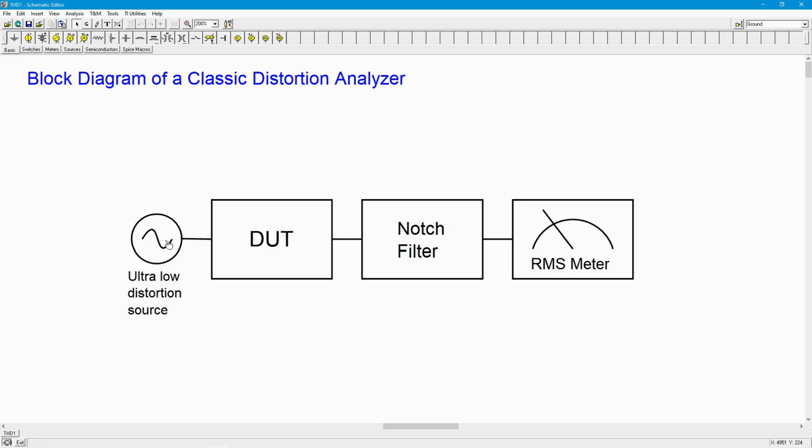So here's an error that some people will make. Let's say, and I'm going to use very simple numbers, that this thing has a 1% residual THD, which would be an insanely high number. I understand that, but this is just for simple mental calculation. I would expect something like 0.001, maybe lower, for a quality ultra-low distortion sine source. But let's just say it's 1%.